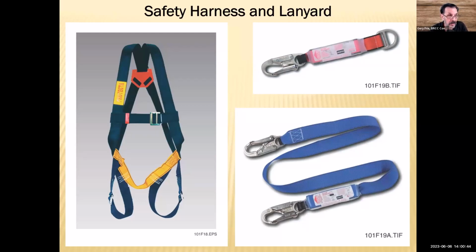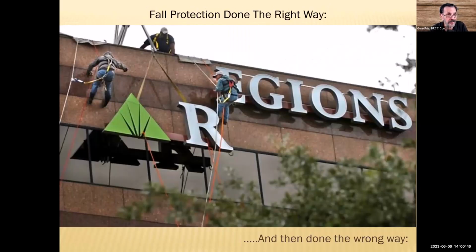However, there is something more like a boatswain's chair that you can sit in, like you see in this picture. That's considered a Class 4 harness. They can support your weight while you work. You have a line that's supporting your weight, the load line, and then the lifeline is there for the emergency. So you can see that these two are tied, with one taking the load, and the other one for emergency use.